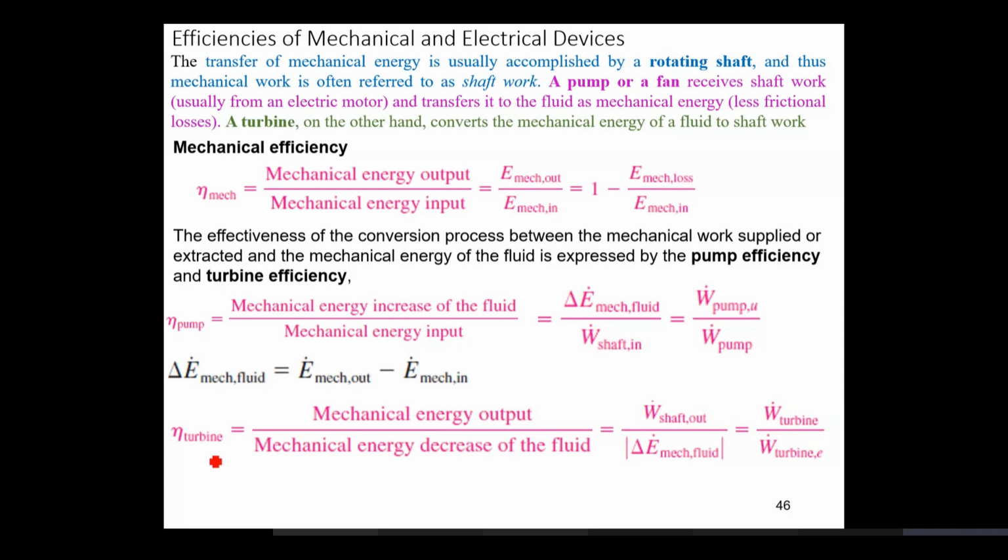So the pressure of the fluid which is required to rotate the turbine would essentially decrease. That means the energy of the fluid would decrease as it enters and leaves the turbine. As a result, some amount of that energy would be extracted, which is in the form of a rotating shaft. Clear enough?